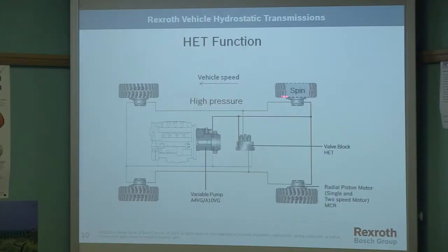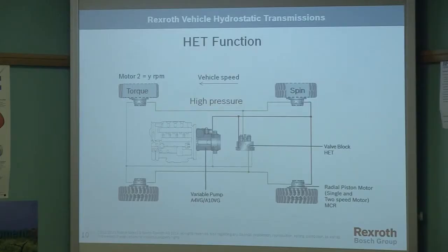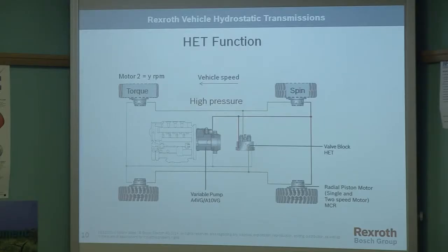Now, this isn't going to spin away out of control and damage the ground or the golf course because it's still in series. It's not like it's in parallel and can take a lot of the pump flow, but there's a fractional reduction in the vehicle speed because we are bleeding this small amount of flow off here. So we've got torque on the front axis. It's going around fractionally slower, but imperceptibly. And of course this works without any driver input. You get traction transferring from the rear axle to the front without any real driver input and without any perceivable change in speed.